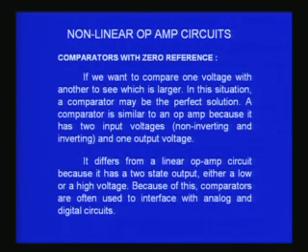In the case of a normal op amp, for example in the amplifier, if there is a sinusoidal wave that I give at the input, the output will invariably be a sinusoidal output. Whereas in this case, if I give a sinusoidal input, the output need not be a sine, it can also be a square wave or something like that. So especially in the case of a comparator, you would see that when I give a sine wave, it will become a square wave, right.